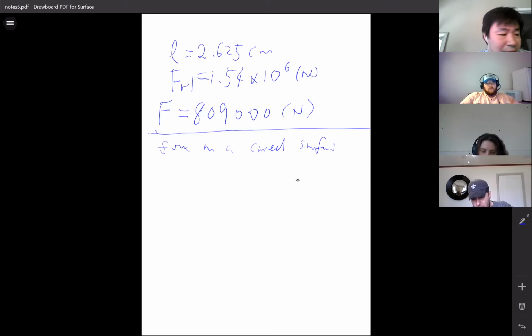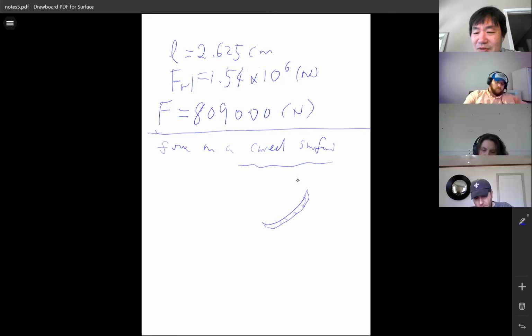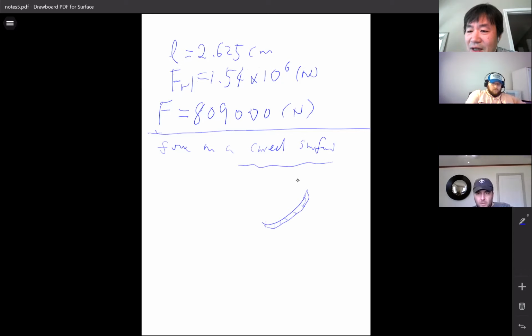Okay, let's come back to the curved surface. Let's see a very simple curved surface. Let's say you have a curved surface underwater. From what we learned in the previous class on the plane surface, we know we need to do surface integration to find the overall force. It's a distributed pressure, a distributed force, everywhere different, right? You have to do pressure times dA, then take the integration to calculate the overall force. That's the standard procedure, okay?